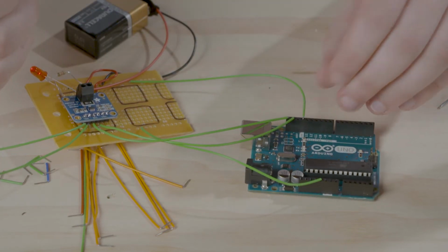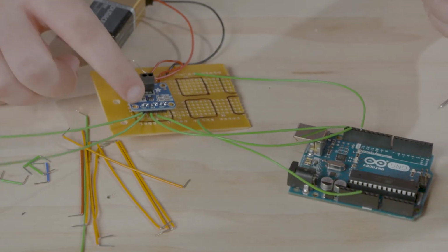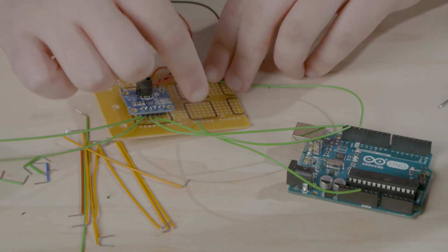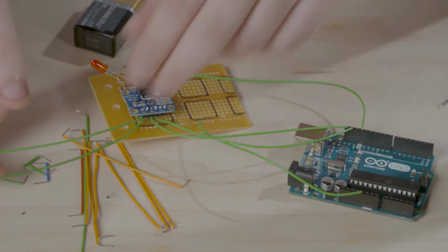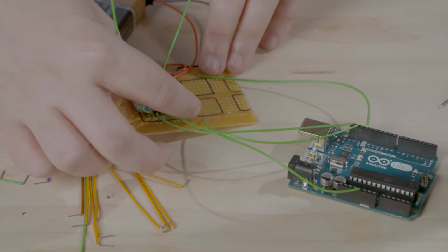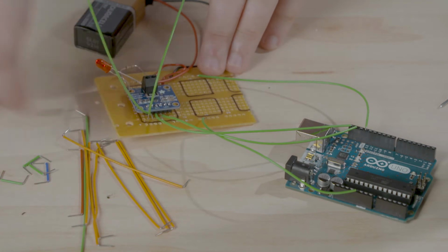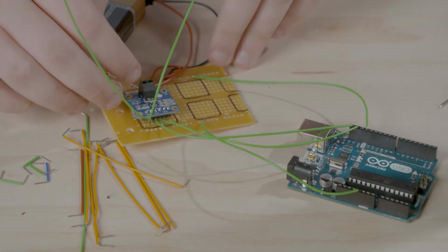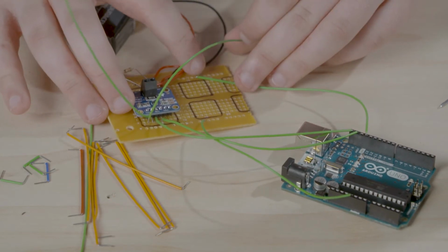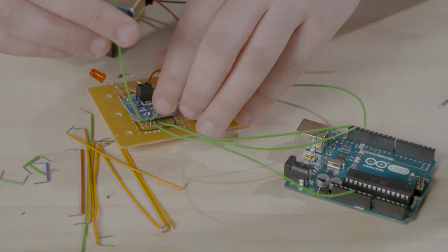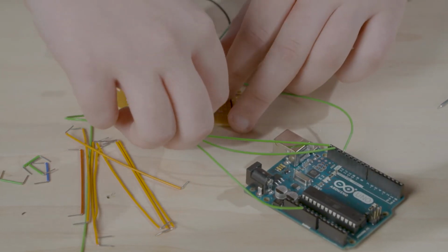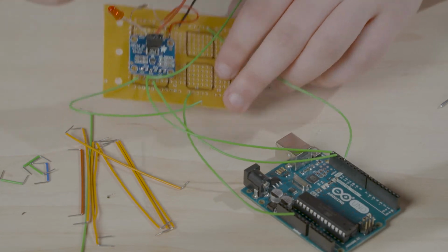Now that I have that, we have to power the current sensor. Now that we have a connection for 5 volts going here and a ground here, we have to take the wires from here, connect the VCC to the 5 volts on this vertical row, and have the ground going to this one. So let's just do a little bend. Try to find a hole that we can attach it to.